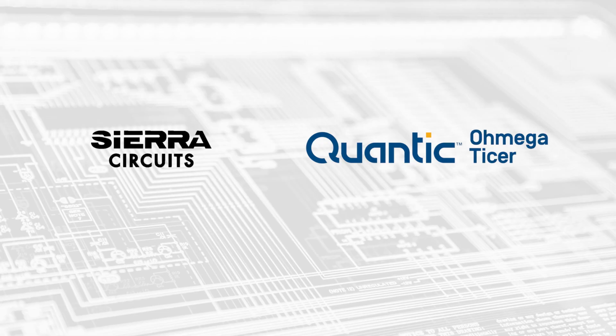Since the resistor material is very thin, most of the resistor material we supply is on 1/2 ounce copper, although it can be supplied on 1 ounce. And so it's typically incorporated right into a signal layer. So the amount of thickness you're adding, I told you, the worst case is 10 ohm per square material, and that's like a micron. So our material really is almost a negligible thickness. Now, if you need to add an additional signal plane, it's just going to be that half-ounce copper additional thickness that you would have to add, but it doesn't add much. And in the case of the embedded capacitor, you actually reduce thickness because of the reduced spacing between the power and ground plane.